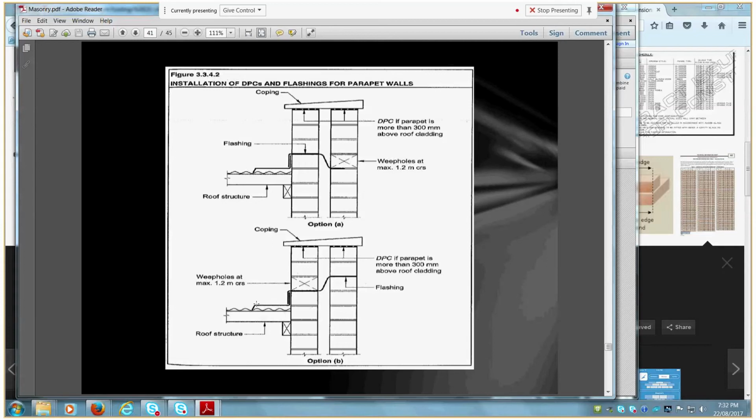So we get our roof laid first, then this flashing goes in, and then that flashing may be installed initially, but then that's bent over. We don't want to have a scenario whereby this flashing goes on the inside of that one, for example, because it's all about ensuring that moisture flows downhill and the overlaps face the opposite direction. What is a parapet? Oh, parapet, that is where you have a wall that extends past the roof line.